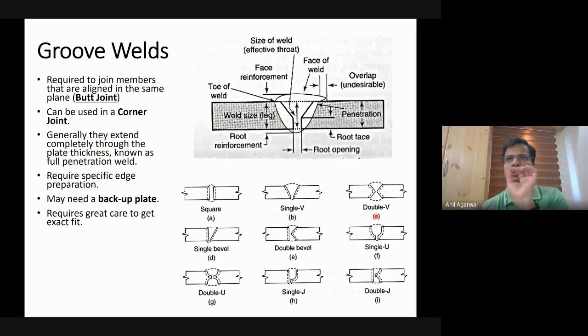But a plasma torch can be used with a higher level of precision. So if you want to cut a groove of a particular width, you can control the amount of energy, or current, that is passing through the plasma torch, and then it will give out a kind of flame which is basically a plasma flame, that is much narrower and much more consistent in its size and length and so on, so that it can be used very effectively in getting a uniform geometry cut.